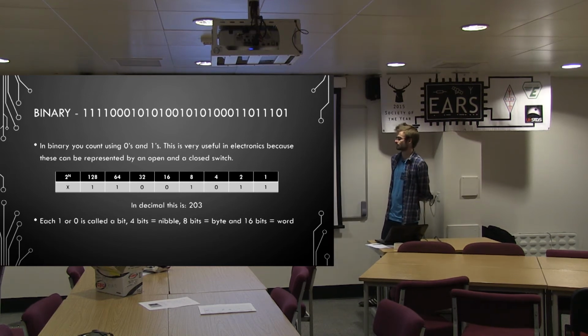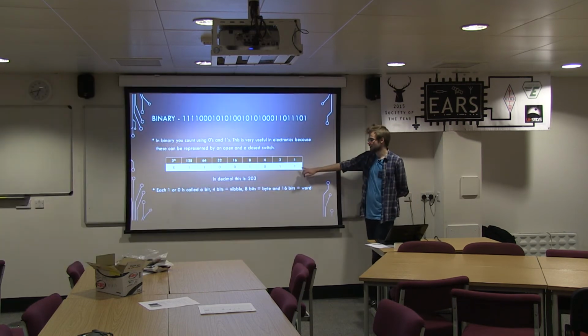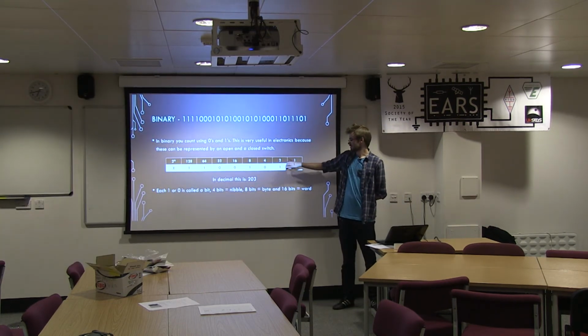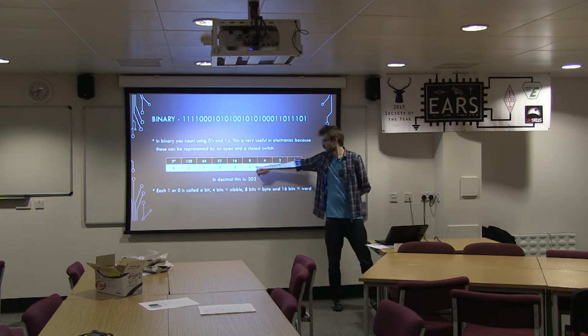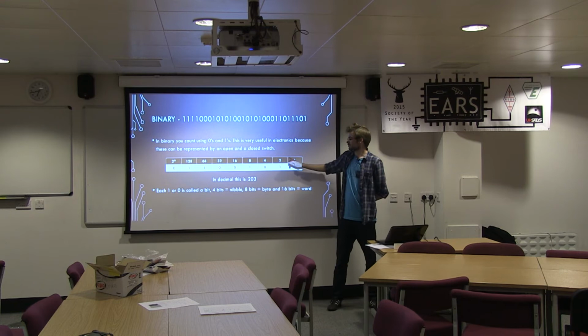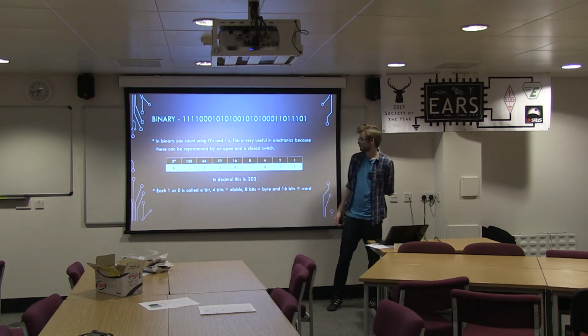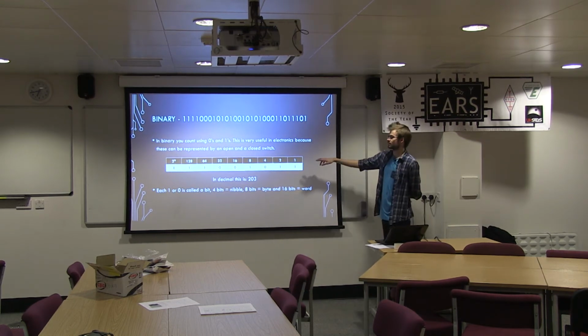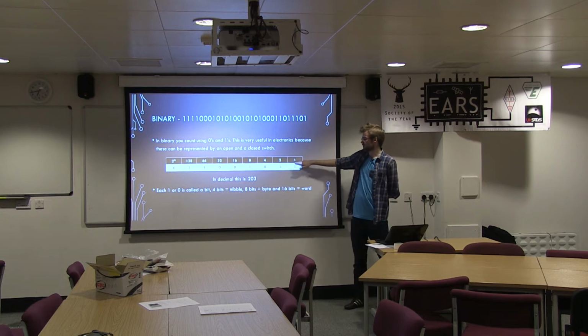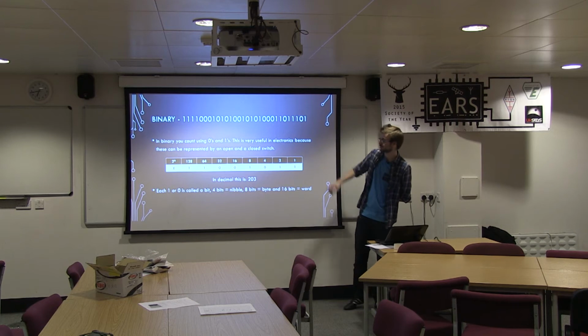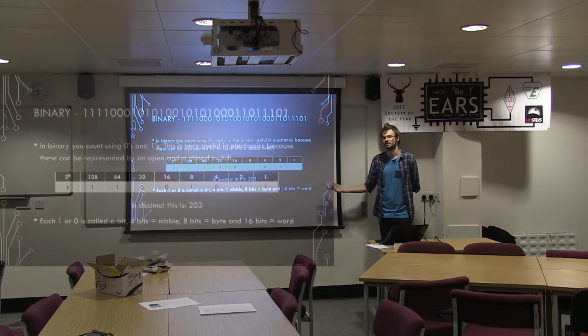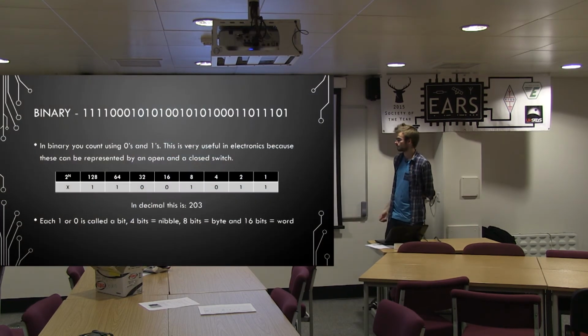So what this allows us to do is it stores the values as each of these bits represents a different number. So if this is 1, then you add 1 to your total. This one is 1, you add 8. So these are all just in powers of 2 increasing. So the way you figure out what number this actually represents is you just add up all of the numbers that correspond with a 1. So you add up the 1, the 2, the 8, the 64, and the 128, you end up with your 203, which is the number it's actually storing.